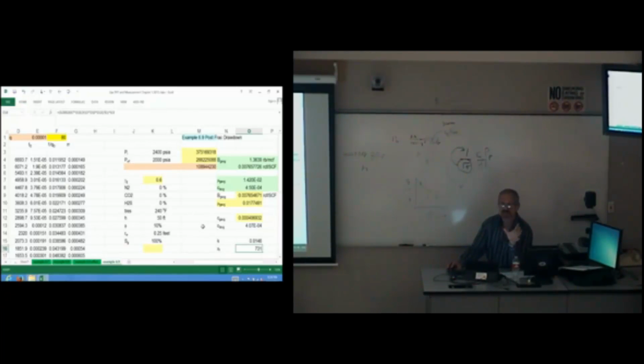Now, this is not transient pressure analysis. This is transient rate analysis. This is chapter 9 stuff. And you might remember the very first example we did was a variable rate drawdown. A variable rate drawdown is transient rate analysis, not transient pressure analysis. So now we've actually done a radial flow and a linear flow transient rate analysis already, even though we're in chapter 6. It's the same. It's just changing the inner boundary condition from constant rate to constant pressure. Okay. That's pretty good timing.